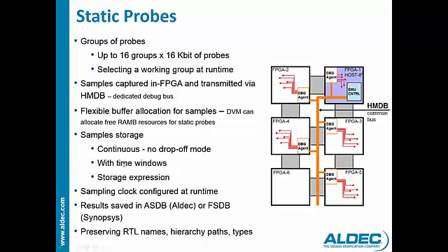Then we've got time windows. To avoid the emulation slowdown, time windows can be used, which means that you can specify how many samples will be captured by the buffer following the occurrence of a trigger. Therefore, a limited number of signals are saved in the memory.